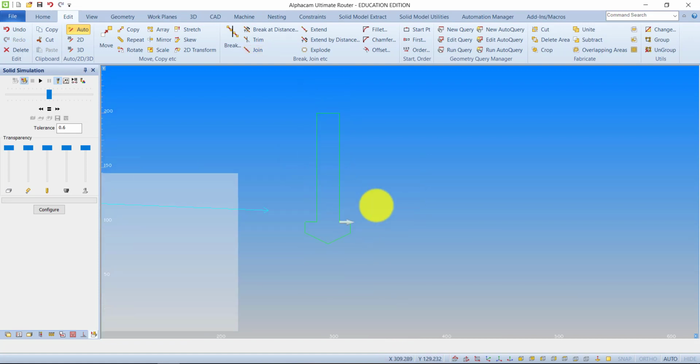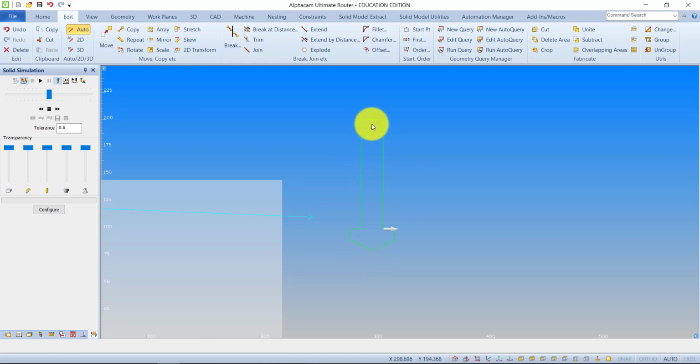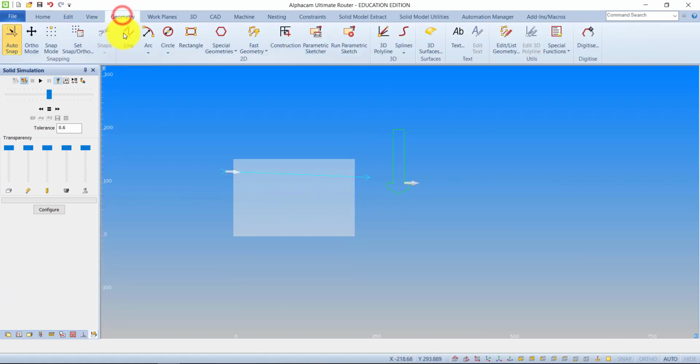That's better. So that was a bit long-winded, but what we have to do is draw the exact cross-section of the tool, draw half of it first, and then mirror it, because it has to be a totally enclosed area. You have to have the cap on it, the top on it there. It has to be one single closed loop, so there has to be only a single ghost tool, and it has to be perfectly symmetrical. While I'm at it, I'm going to go to Geometry, Line, and just draw a line across the piece like that.